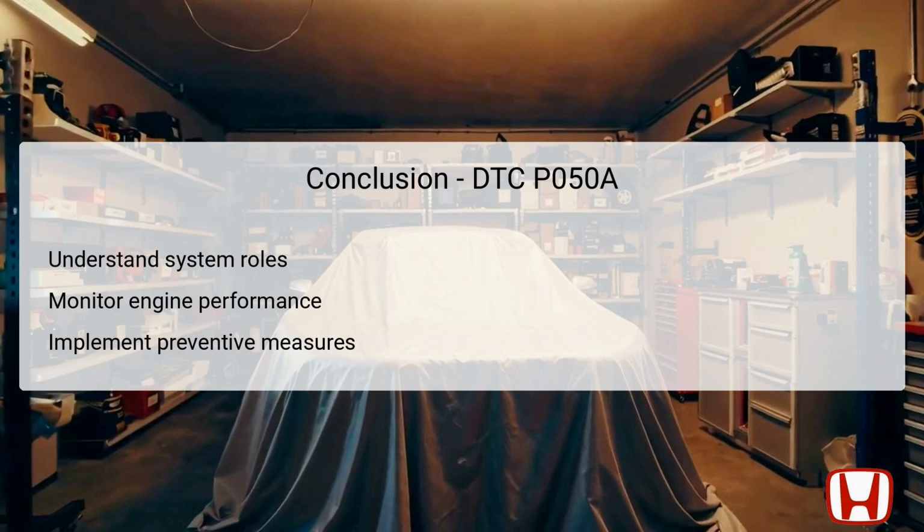In conclusion, addressing the DTC P050A involves a thorough understanding of the roles of various components such as the PCM, IAC, and sensors like the ECT and IAT. Monitoring engine performance is essential, especially during cold starts, to detect any irregularities early. Implementing the troubleshooting steps outlined ensures comprehensive diagnostics and repairs, effectively eliminating the DTC.